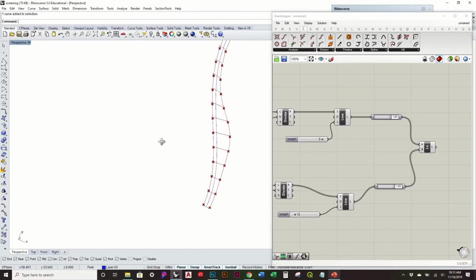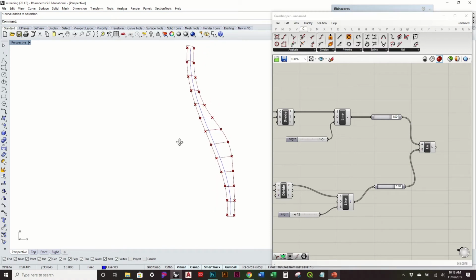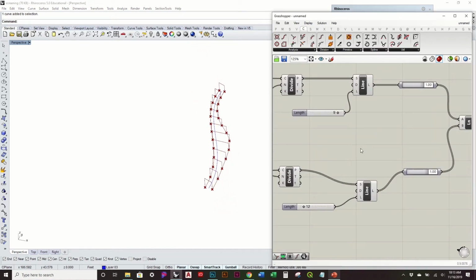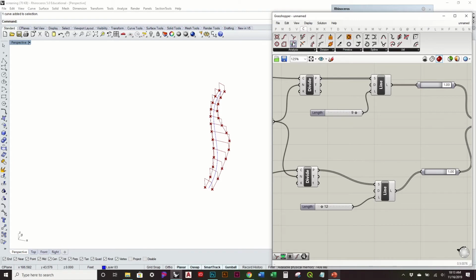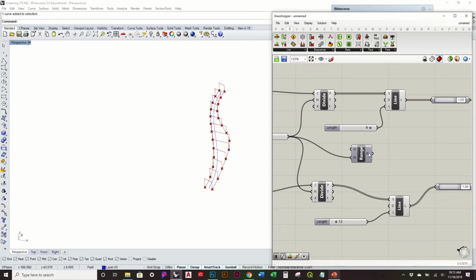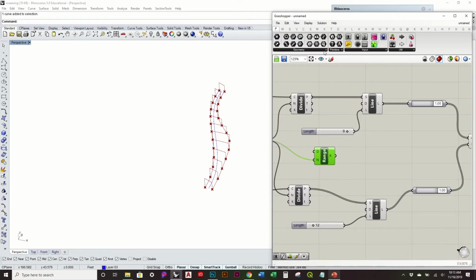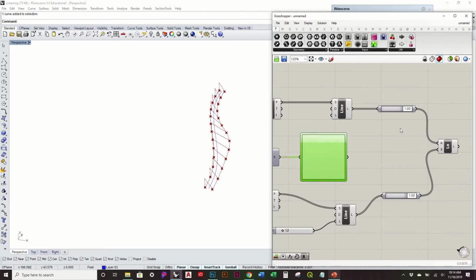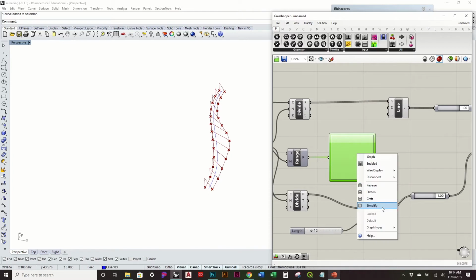So what I might want to start to do is, again, mess with this length. So I'm going to, again, use the Sets, Range. Again, I'm going to use the same amount. So 13 values, 13 points. Parameters, input, graph mapper. I'll just give myself a little more room here. And in this case, maybe I use something like the sine curve.